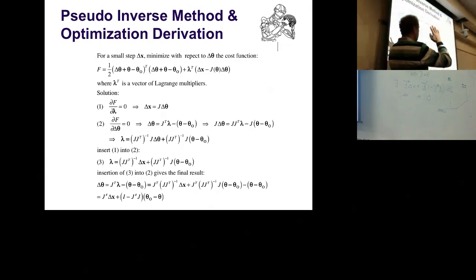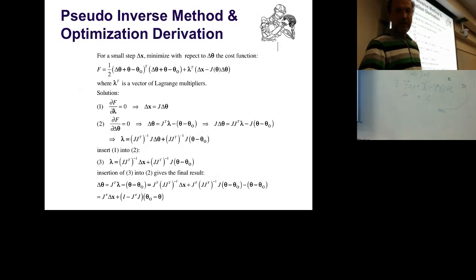Again, very important. Because we have a system with too many degrees of freedom, it's a redundant system. Whenever we create a solution which makes a decision how to use these degrees of freedom to reach in this lower dimensional space for the target, there has to be some principle behind that, how we choose a particular solution among the infinite number of possible solutions. All I try to repeatedly tell you is that this most of the time can be grounded in some optimization criterion which generated the solution. Which then tells you that, in general, you can go to optimization and create even more complicated optimization criteria with inequality constraints and other things to create other solutions for inverse kinematics. And this is where convex optimization and quadratic programming come into play.